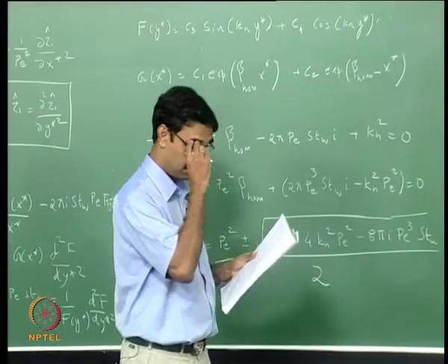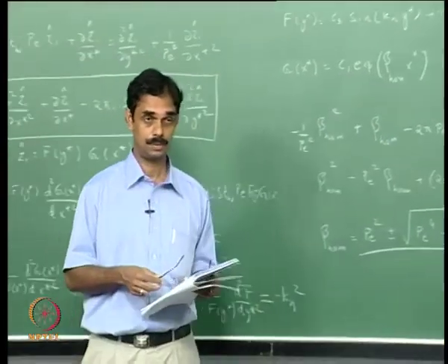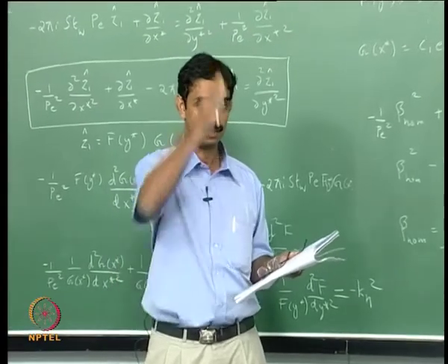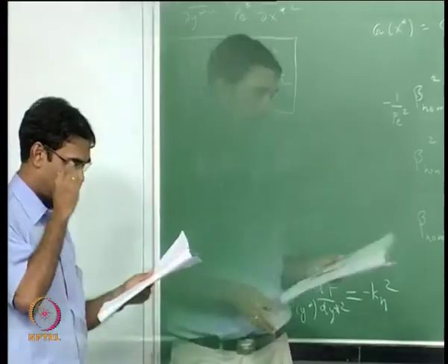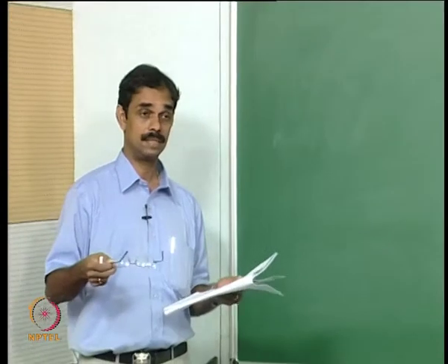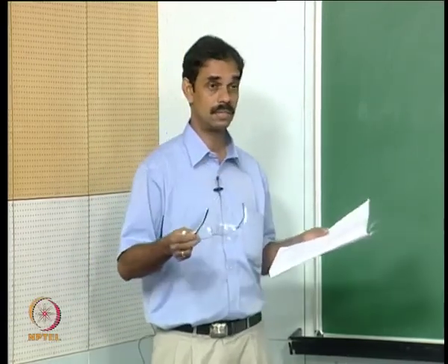Now all we need is to find the coefficients that we can get from the boundary condition at the inlet plane. So since the mixture fractions are fixed, we said that at the fuel slot Z is 1, at the air slot or the oxidizer slot it is 0. So there is no fluctuation there.